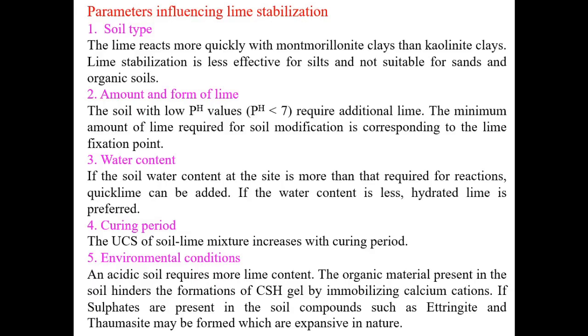If sulfates are present in the soil, they may react with calcium and carbonate of lime and form compounds such as ettringite and thaumasite, which are expansive in nature. So, due to these compounds, the treated soil will be subjected to excess swelling than that of untreated soil.